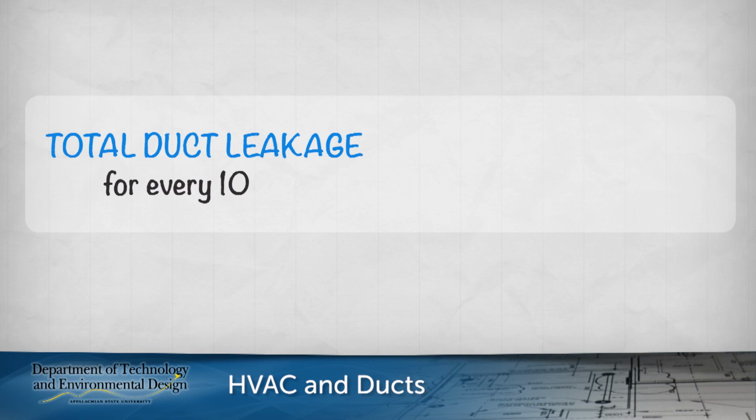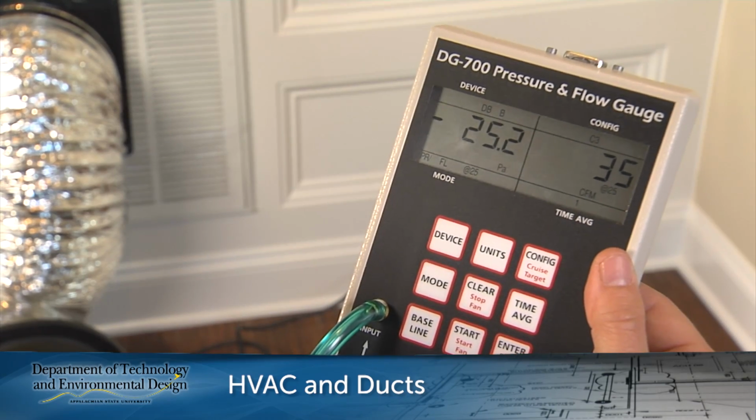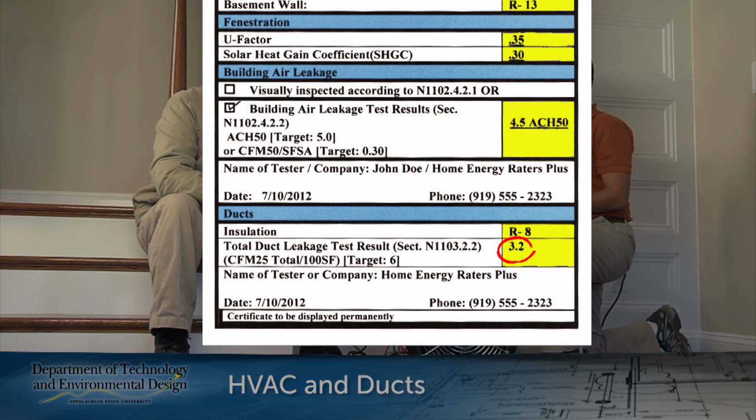For duct testing, which is required, total duct leakage must be less than or equal to 6 cubic feet per minute for every 100 square feet of conditioned floor area, when tested at a pressure differential of 25 pascals. The results must be noted properly on the Energy Efficiency Certificate.